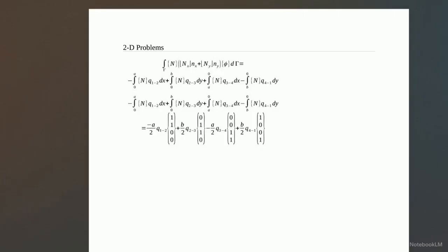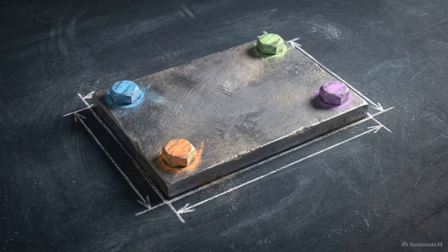Returning to the math, that single gamma integral decomposes into 4 separate edge integrals, isolating the specific q flux crossing each boundary segment. Evaluating these edge integrals gives us a series of column vectors, scaled by exactly half their edge length. These 4 calculation outputs translate continuous physical loads applied along the edges directly into discrete numerical values assigned to the 4 corner nodes.